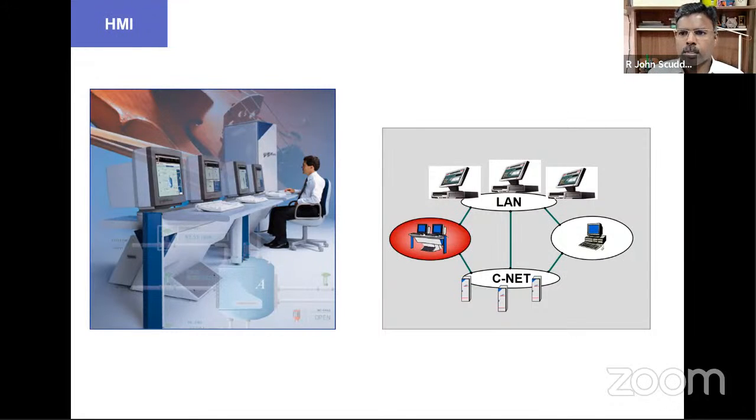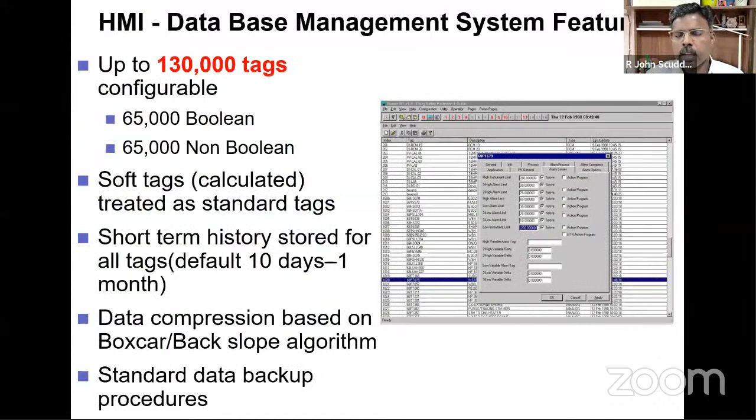This is physically what we have done in our power plant also. Not only that, sometimes the feedback comes up, but actually the pump has not started or the motor has not started. So we also give current parameters. Before the command was given, the current was 0. Now the current has risen, and we put the current in a graphical trend form, where the current rises within a rectangle like this. So everything is visually very, very easily understandable.